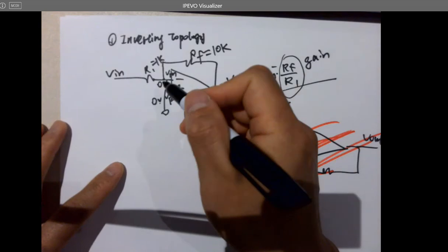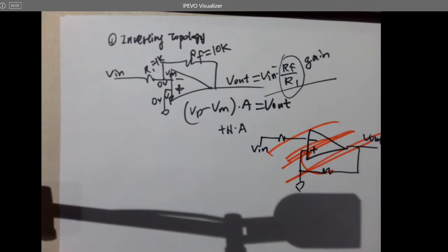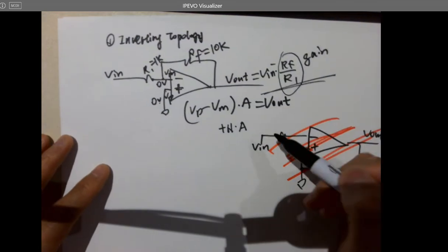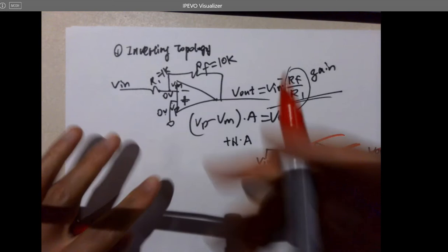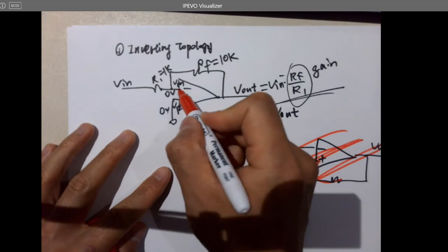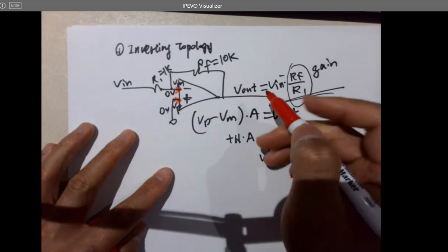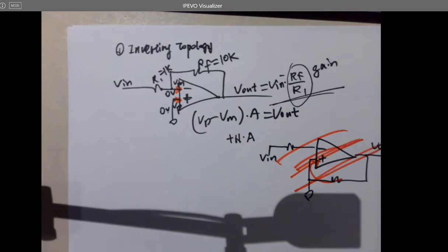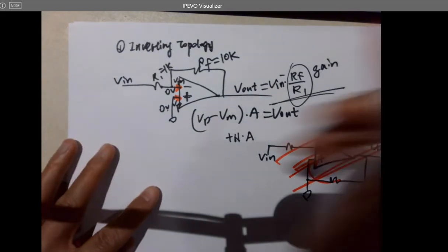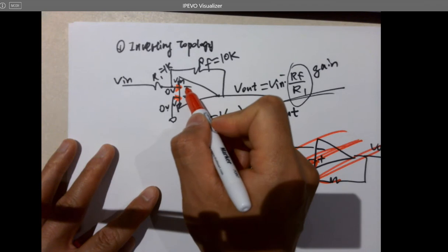So how to derive the voltage gain for this one? Why is it this, right? So the way to do that is, also one thing you need to know for OpAmps, there's no current flowing into the OpAmps. That's pretty interesting. We don't want to just derive everything and draw the circuits for you guys, but memorize it right now. So the currents are not being injected into the OpAmps.